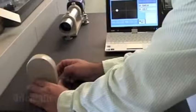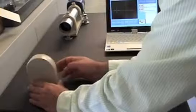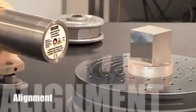Now we need to set the orientation and tracking. What we want to see is when the mirror tilts backwards and forwards, in other words going up and down, that the autocollimator is set so it also measures just up and down. How I normally do this is if I move the mirror, if I twist the mirror left to right, we should only have one axis on the autocollimator moving. The second axis should remain stationary. Alignment.